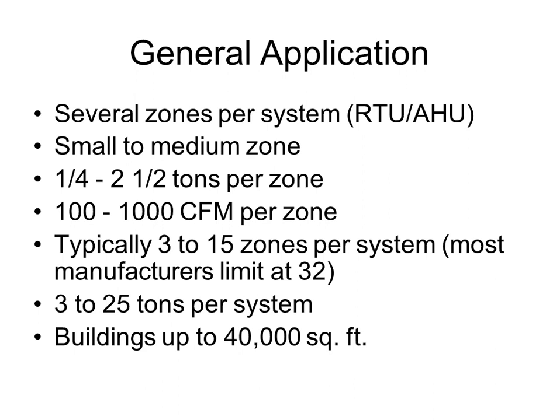That being said, if you have a customer who wants to zone every single office individually, you could have more than 15 zones, and they could all be 1/4 ton zones, and you could have a 5-ton air handler on there or something, but with, I don't know, 30 zones. But that being said, you don't usually run into it, so we kind of say 3 to 15 is a general guideline. 3 to 25 tons per system, per VVT system as a general guideline.